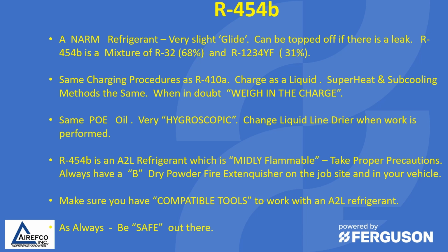The same charging procedures as 410A apply. Charge as a liquid, superheat and subcooling methods are the same, and always, when in doubt, weigh in the charge. We're working with the same POE oil. It is very hygroscopic, so make sure you change the liquid line dryer when work is being done.